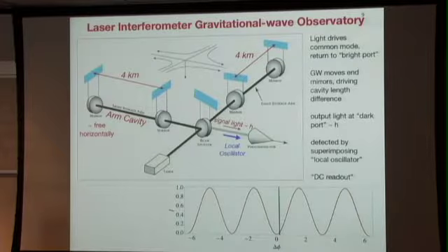The reason why you only want to be a little bit offset here is that the laser noise of this laser will still pretty much cancel out from here. It doesn't really come out with a big fraction. It's only a tiny little bit of laser noise coming out. And then some of this carrier light comes out as a local oscillator. Therefore, this suppresses the laser noise.